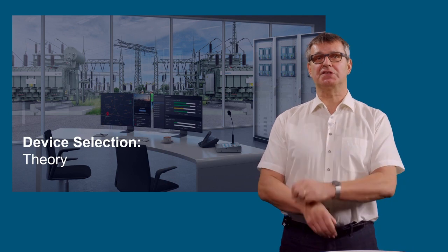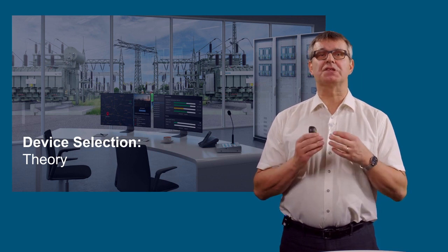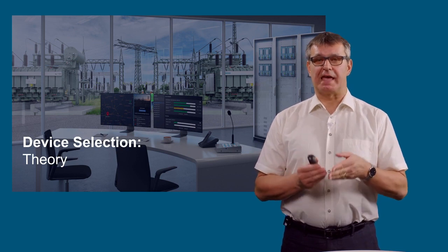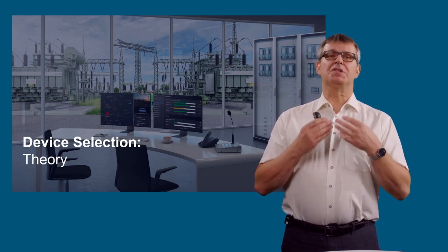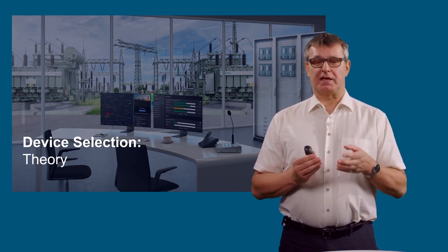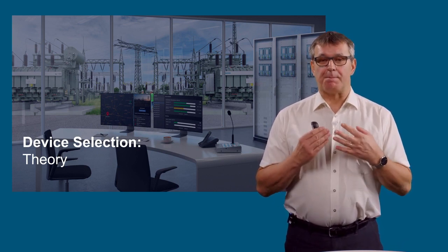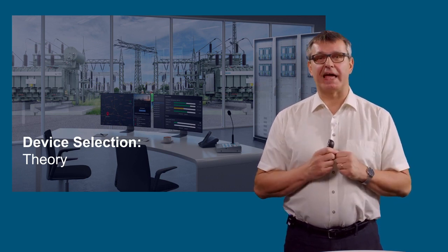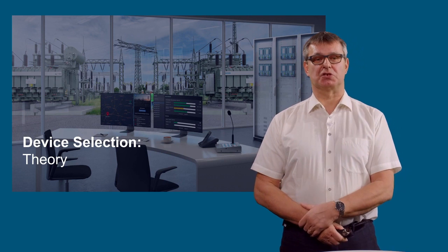But what is possible is that each modular Siprotec 5 device can be used as a bay unit for the distributed busbar protection. So of course you can use a line differential protection device, a 7SL86 or 7SL87, with the integrated line differential protection, and integrate it in the functionality of the bay unit of the distributed busbar protection. Then you have the line differential protection. Maybe this question was more in this direction.